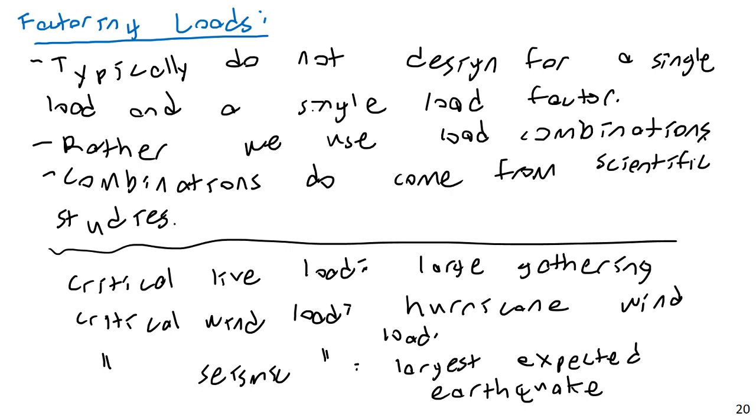So your building must be able to withstand earthquake, it must be able to withstand hurricane, but it's a bit absurd to worry about both happening at the same time. What are the odds that the earthquake of the century is going to strike at the same time as the storm of the century? Yes, there is a non-zero chance of that happening, but it's so low. Again, if we design buildings for that, we would never be able to actually use them or afford to build them.